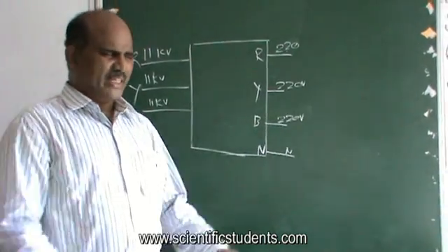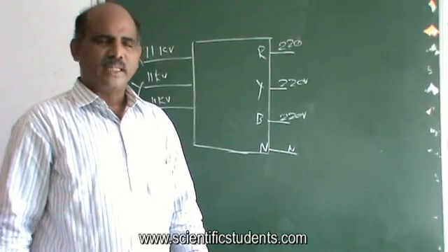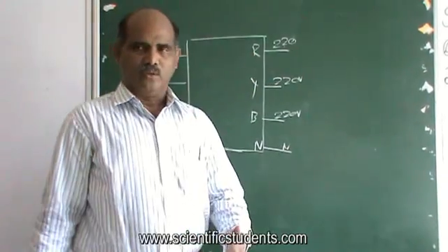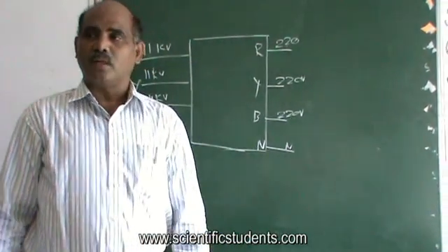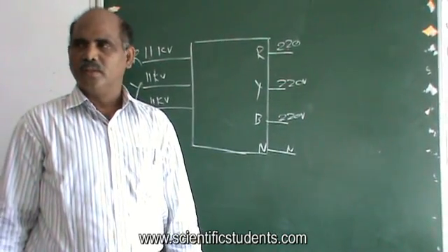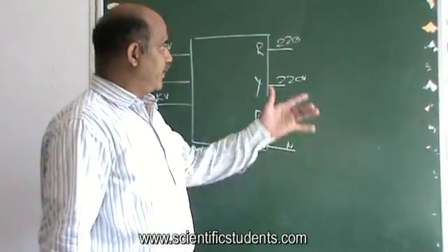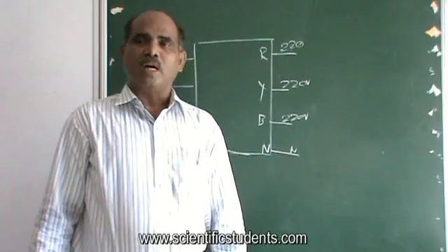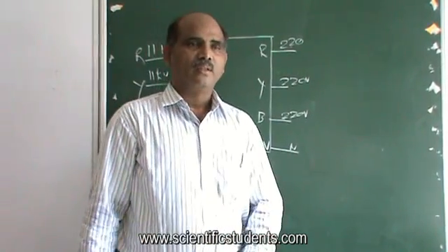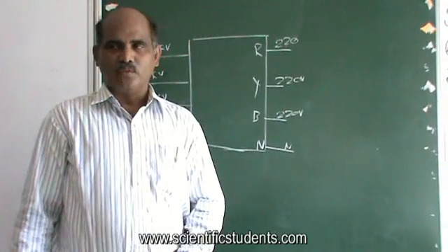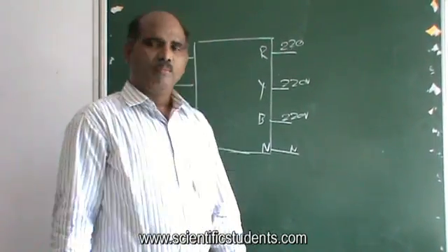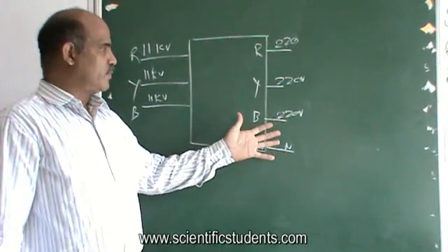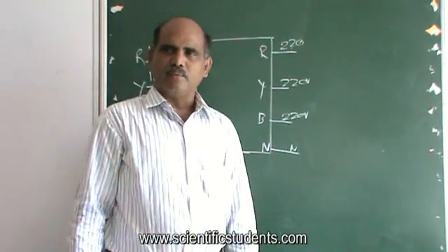So on 220 volts they draw more current. That's why, instead of using neutral, they use all 3 phases. They are called 3-phase loads. That motor itself is called a 3-phase load, not a single phase load. So a 3-phase load doesn't require the neutral. However, the operating voltage of the 3-phase load is going to be 415 to 440. Single phase loads will be working between 220 and a maximum of 250. That's it.